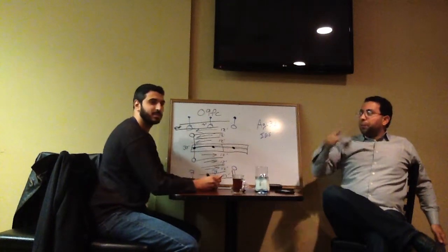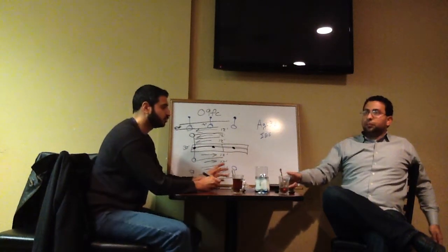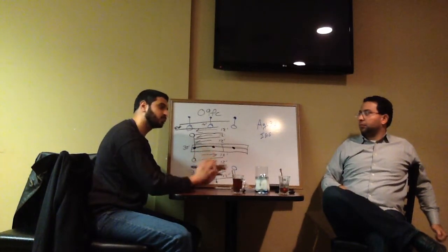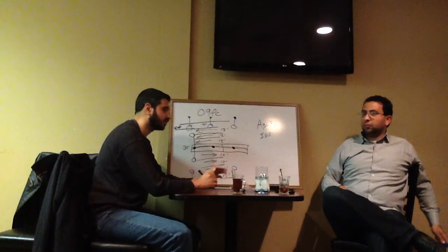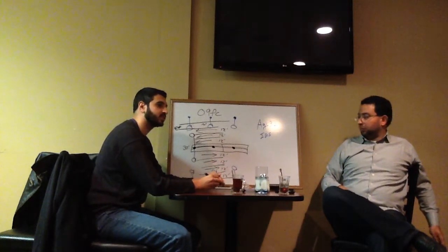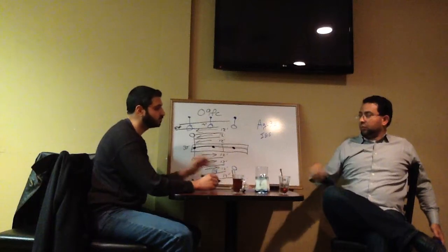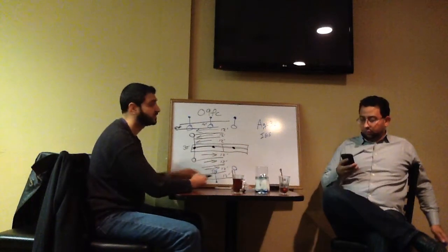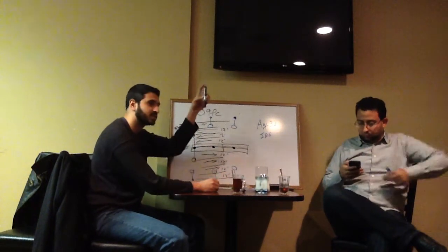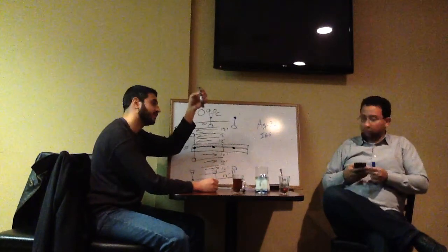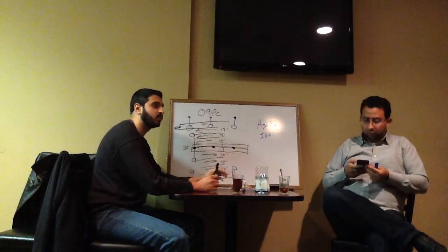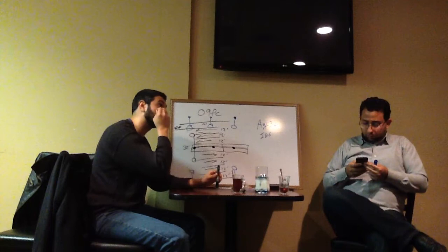So once we get the IES file, I guess without the program it's kind of hard to see, but if you try to run a calculation, it'll just flat out deny you, so you have to load an IES file first. So you go file, open, you attach this IES file for the job, and the first option you're going to hit is how's the mounting for the light. You have to tell it whether it's suspended, hanging, called pendant mounted, pole mounted, attached to a pole, or other options like that.